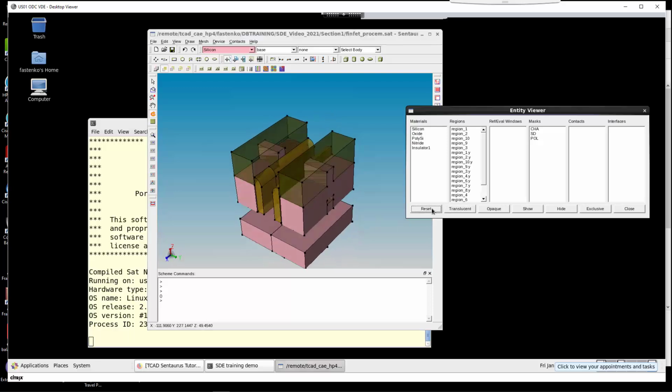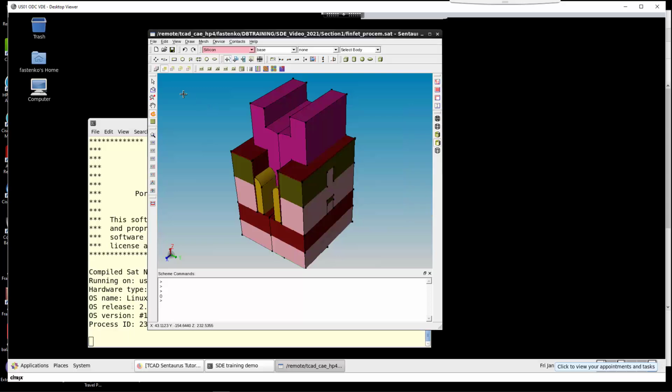As an example, let's create a simple 3D structure using geometrical primitives and geometry manipulation functions and briefly touch the scripting. This is a good time to mention that the geometry operations in Centaurus Structure Editor are based on the ASIC geometric kernel. The ASIC 3D Geometric Modeler is an object-oriented 3D geometric modeling engine from Spatial Corporation. At its core, Structure Editor shares a lot of functionality with other CAD tool and solid modeling tools. As you will see in a few moments, scripting is based on the Scheme scripting language.